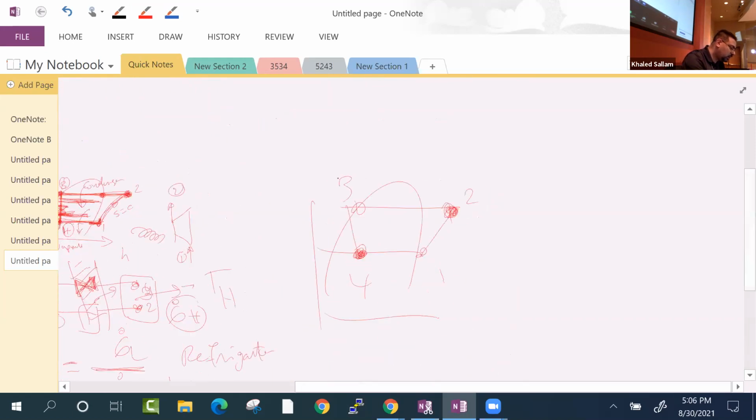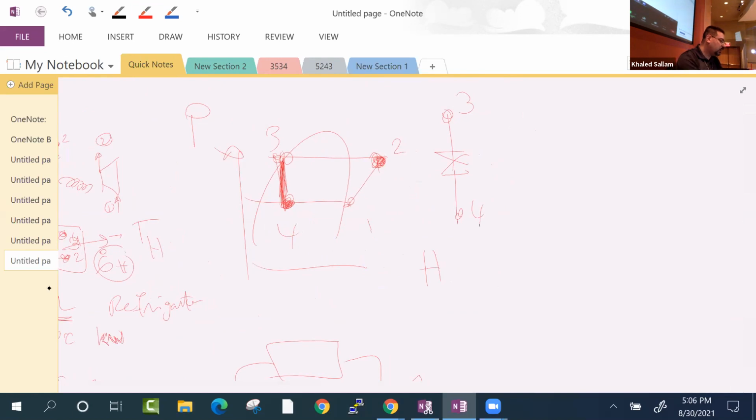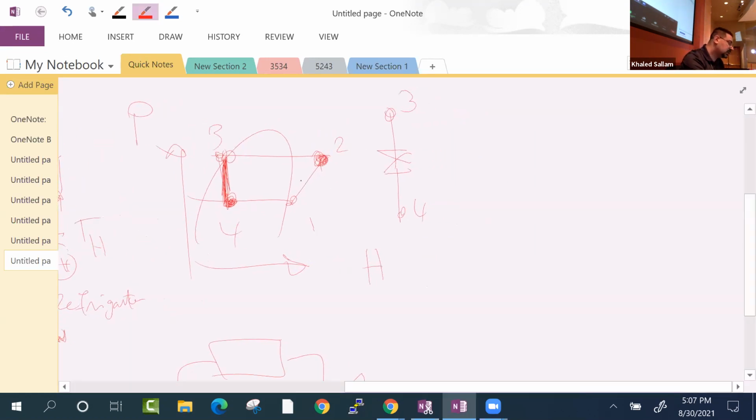So by the way, did you see how on an H-S diagram, 3 and 4 are vertical? What does that mean? If the flow in the throttling device shows up as a vertical line on an H-S diagram, what does it mean? Not isentropic. You think it's isentropic because you think, see, this is isentropic. This is constant S here.